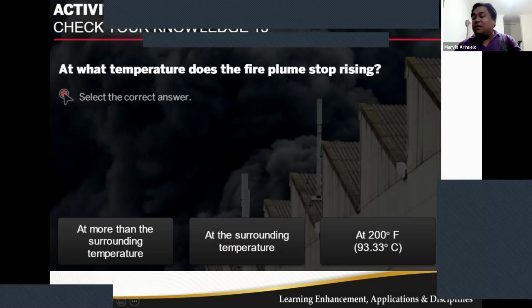That's why, guys, I remember when I was in a warehouse building, where the ceiling is about, I think, 16 meters or 18 meters high, we have what we call a smoke beam detector at a lower level, because of this effect of ceiling jet.